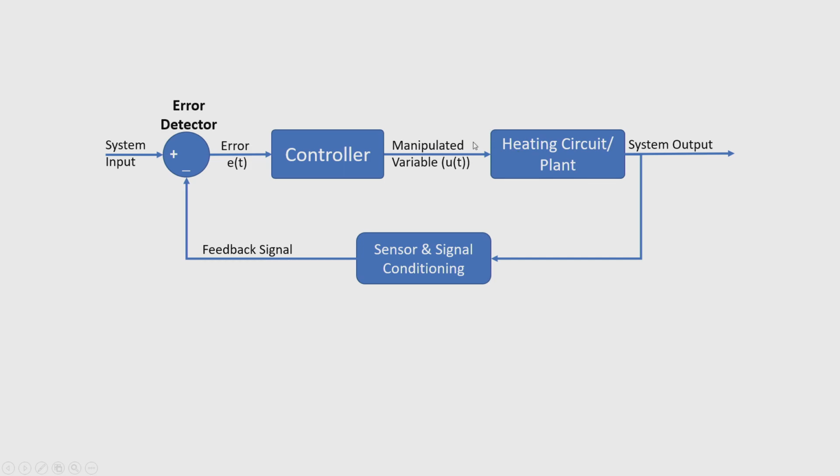But unfortunately, sometimes the manipulated variable given by the controller may drive the plant, or sometimes it may not. So, in order to make the output of the controller compatible with the heating plant, we require a driver circuit.